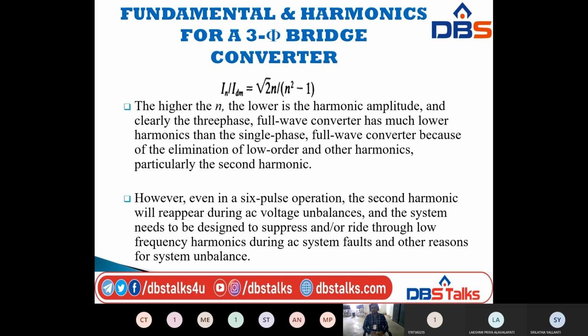However, even in a 6 pulse operation, the second harmonic will reappear during AC voltage unbalances, and the system needs to be designed to suppress or ride through low frequency harmonics during AC system faults and other reasons for system unbalance.